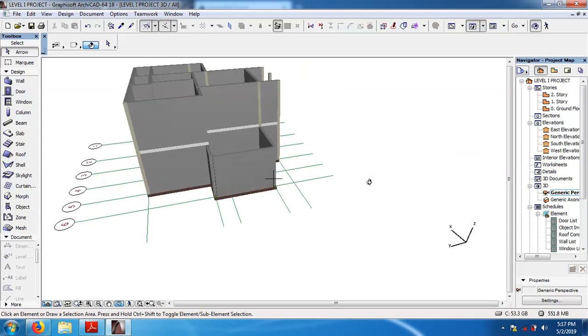So that is it. I want you to work on your slabs. I want you to change their properties. I want you to learn using the advanced technique of designing a slab that assumes the shape of your floor plan using the add polygon command.